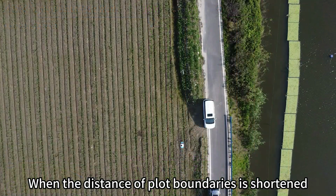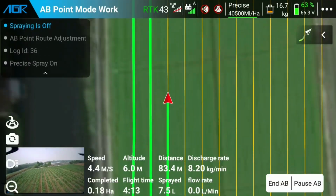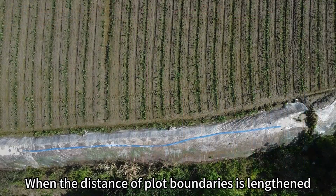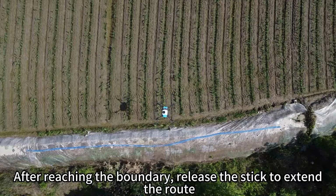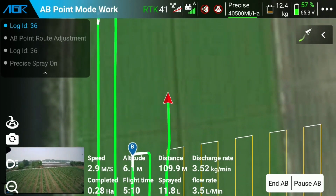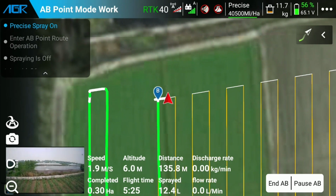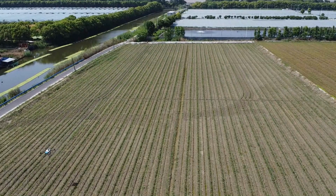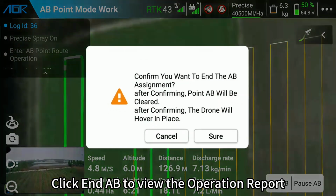When the distance of the plot boundaries is shortened, we can push the stick in the opposite direction of the flight to shorten the route. When the distance of the plot boundaries is lengthened, we can push the stick in the flight direction. After reaching the boundary, release the stick to extend the route. Click AB to view the operation report.